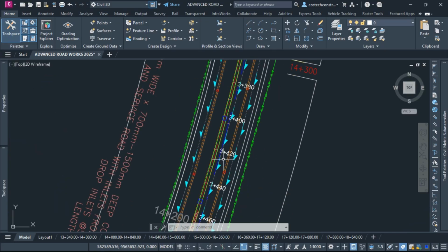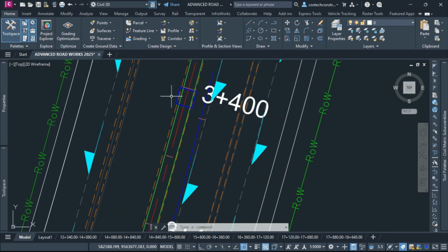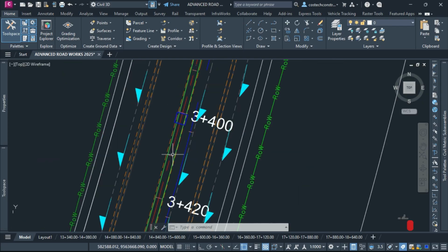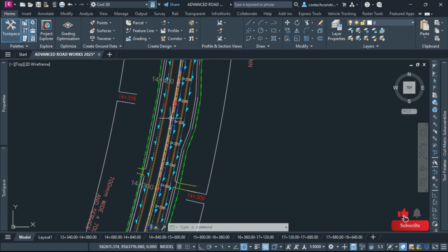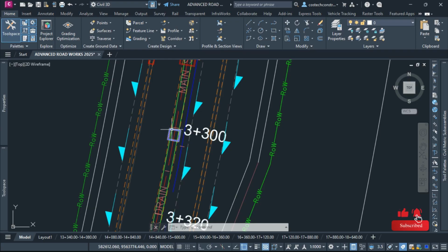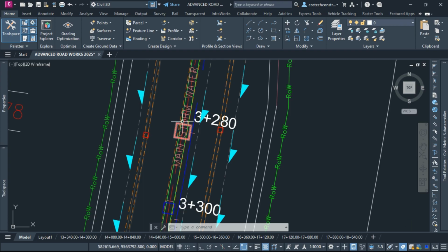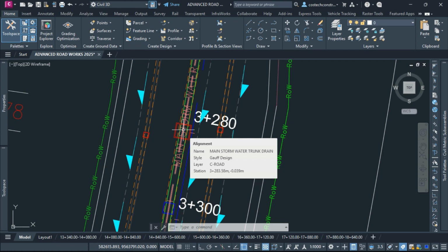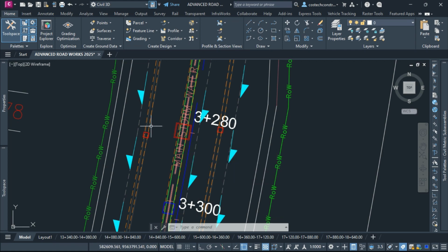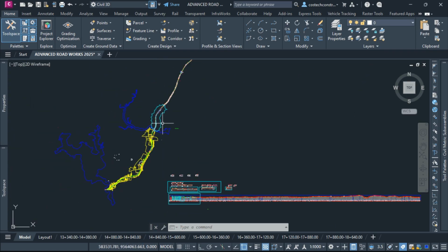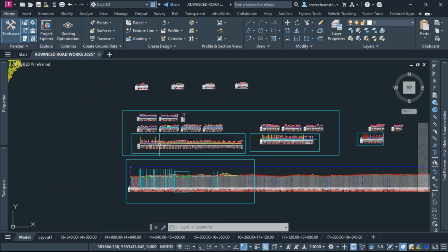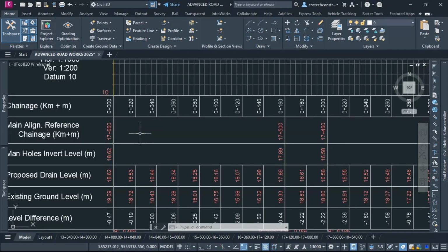This drawing contains manholes and road plan detailed as polylines and we will be recreating our sewer and road designs with the provided data. The blue manholes have been arrayed at 50 meters interval along the design route. The main stormwater trunk drain alignment represents the pipe route and specific manhole locations for our sewer design. We can identify the manhole detail at station 3+283 from our sewer profile view below.